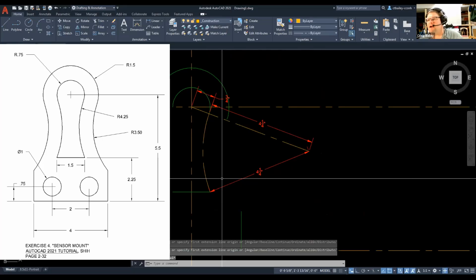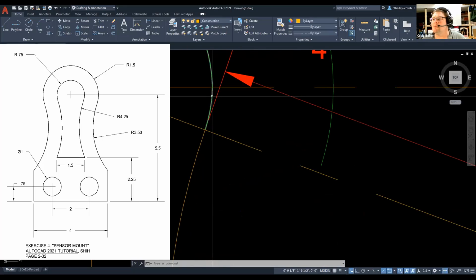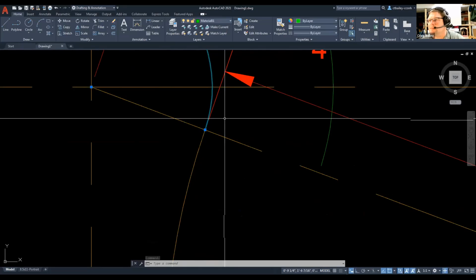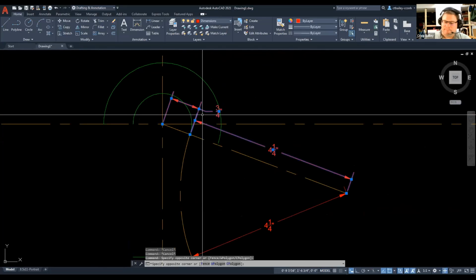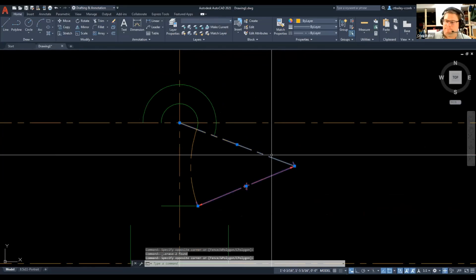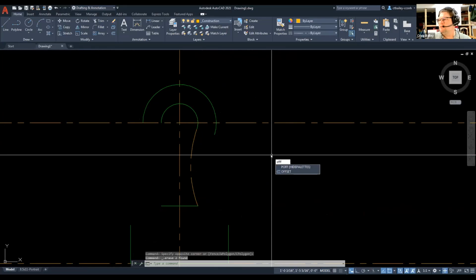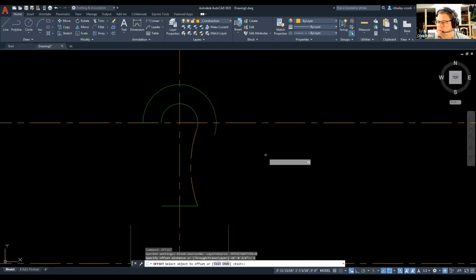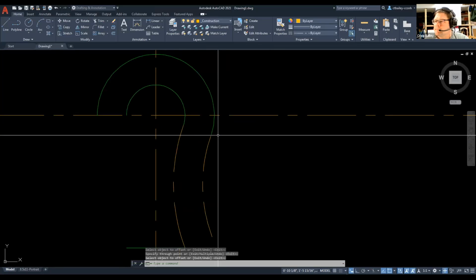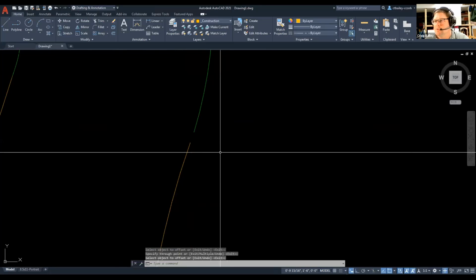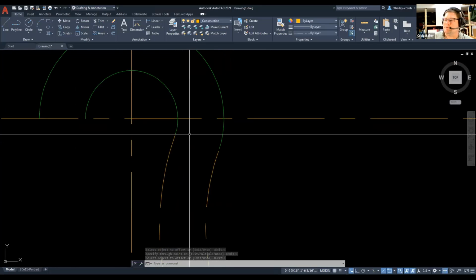See, that really wasn't that hard, and it was not a how do you solve it as a tangent circle. It was how do you solve it with the geometry, and yeah, all right, cool. So now we can just bang this thing out, right? And so we'll offset. Use the offset command. I'm going to use the T for through option. Pick the inside guy and put it through that point there. And the offset, even though it doesn't actually go through it, it still geometrically does.